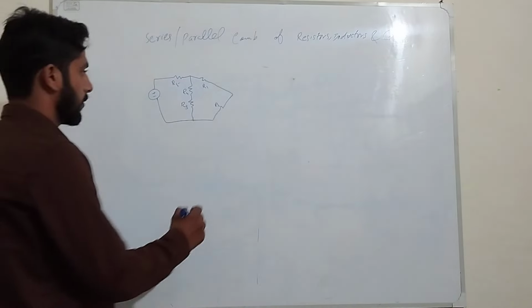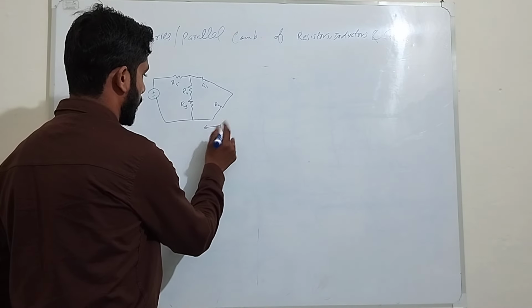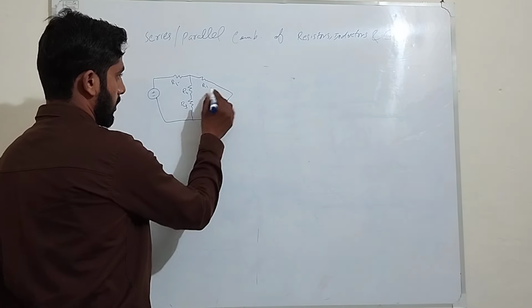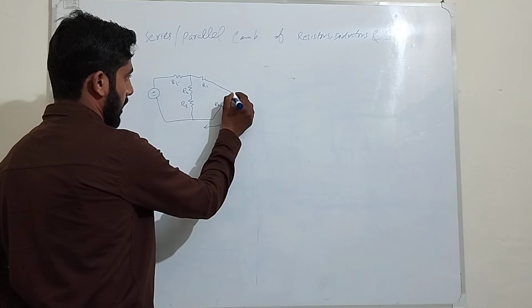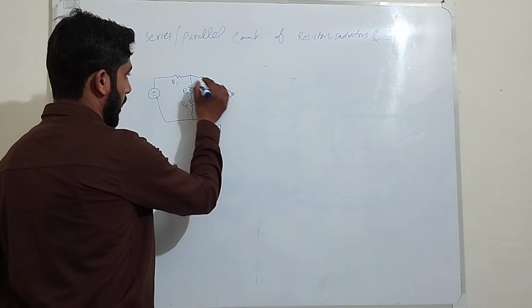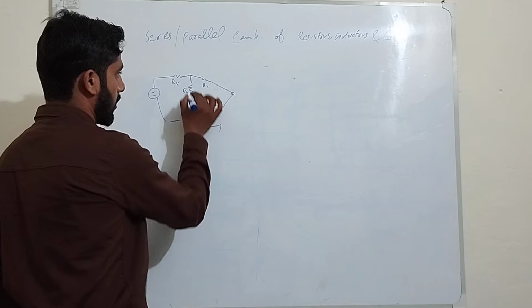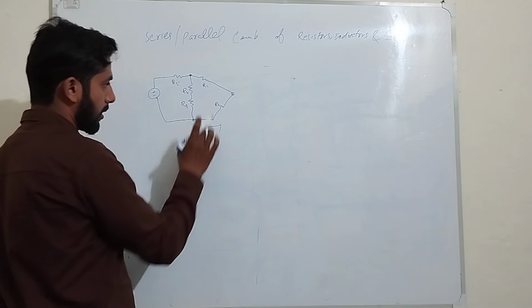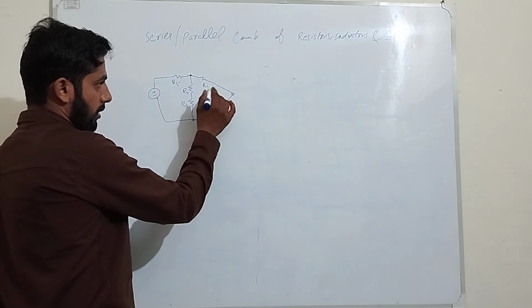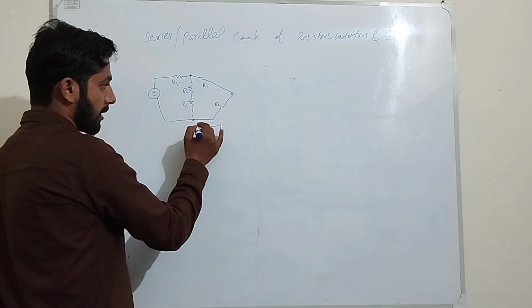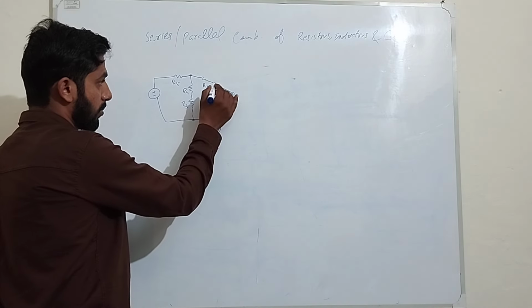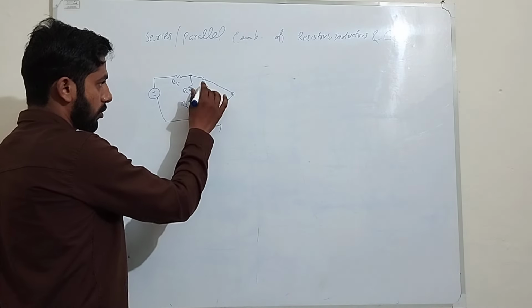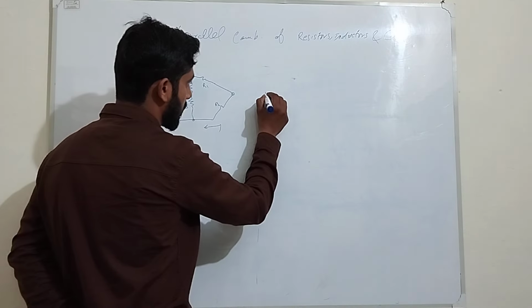See here, at first step I have to evaluate from load end towards source end. Two resistors have one common point and two distinct points. This is another way to identify them. Two or more resistors with one common point and others at distinct points will be in series, because it's end to start here. So R1 and R2 will be in series.